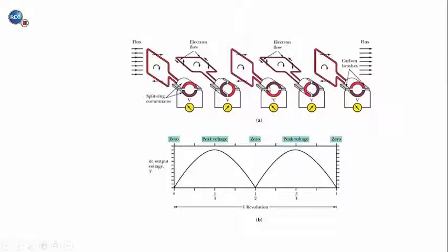Now at half of a revolution, that's when the brushes are at the gaps of the commutator, and as the coil continues to rotate, now the red part of the commutator is connected to the left brush. And so now this part of the coil that's on the left, as it moves up through the flux lines, the current is going to be induced out of the page.